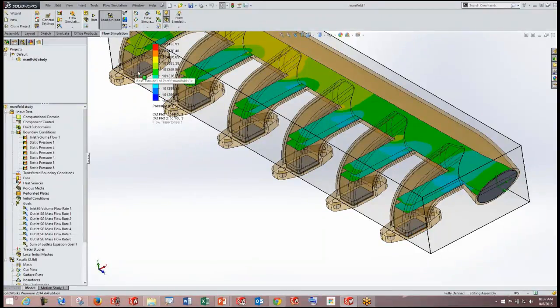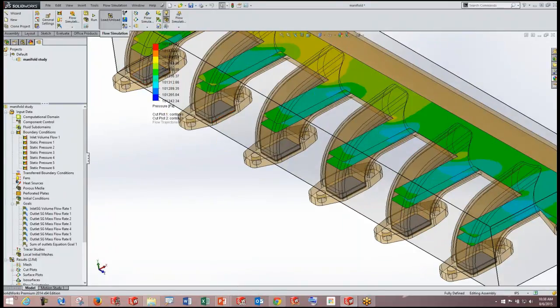Now, one thing you can do is you can have a dynamic pressure. So here, where this is just the environmental pressure, you could say the pressure is X, and then you can change it to be any other pressure over time. So that might be a way to do what you're talking about there, to change what the pressures are at each one of these outlets so that it simulates the same type of thing. Yeah. Okay.